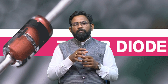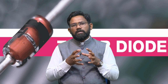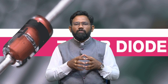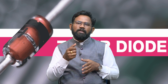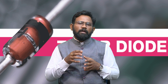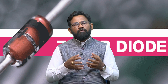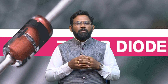So, from that we have checked for the given circuit the voltage value V. It is coming out to be 80 volt. So, from that first we have concluded that the Zener is in on condition, since the value of V is greater than Vz. So, the output voltage was 50 volt and the drop across the R was 70 volt, and by applying Kirchhoff's current law in the circuit, we have obtained that the Zener current flowing is 9 milliampere.